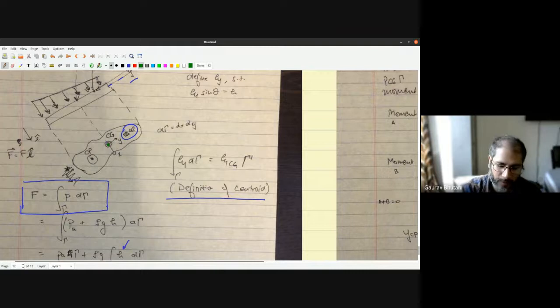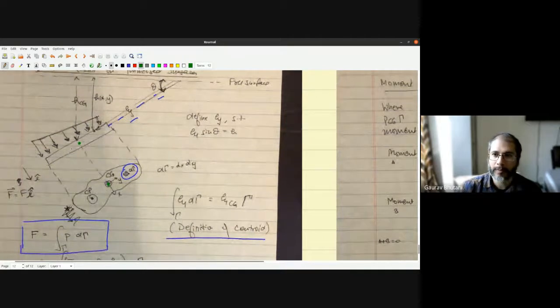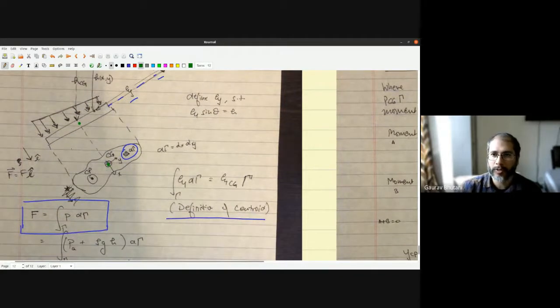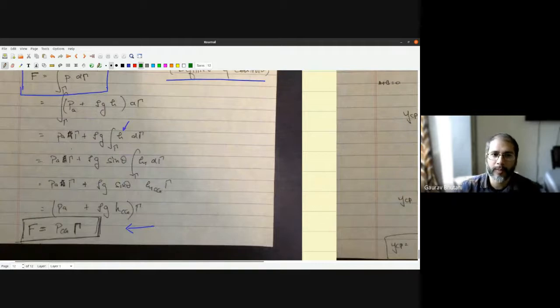And that is again easy because for the center of gravity, you can calculate the height of the center of gravity from the surface of the liquid, and then simply multiply the hydrostatic pressure at hcg times the overall area of the surface. It's that easy. No need to integrate. When you integrate, ultimately this is what we get. It's a very important relation, a very powerful relation. So it's worth knowing if you're working with hydrostatics. Is that clear?